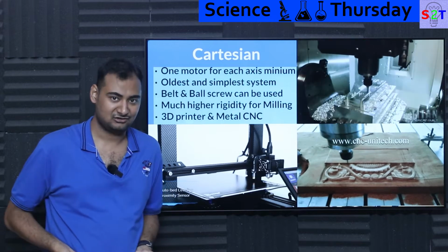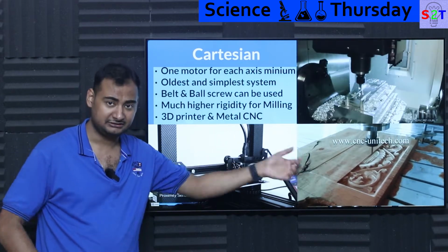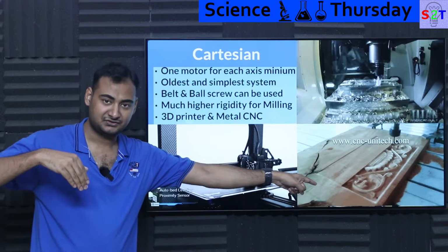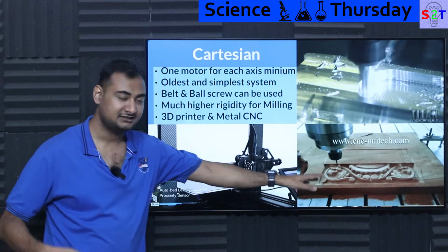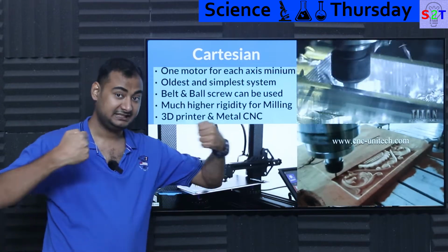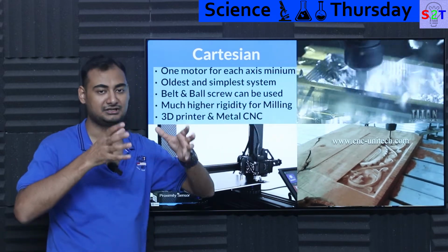Laser, there is no physical contact, so it simply does not care. But the moment you are going at even wood, if you're carving it, the drill bit is going against the wood, action equals reaction, so the wood is fighting back. Now that simply means that vibrations, basically the impact, will be transferred into the motor. That motor will transfer it to the caddy.